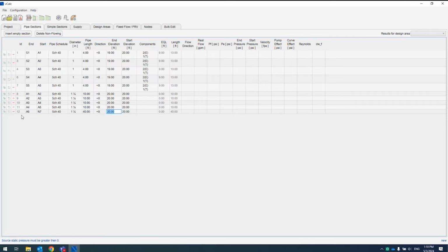So at this point, you can continue working your way back out the system. So maybe we're going to go one extra node here. We're going to go from 20 feet to 19 feet. We'll say it's still a 1.5 inch riser nipple, and it's 1 foot long. And then we can go from there, work our way back the mains. So maybe it's a 3-inch main. We'll just say it's 80 feet long. We're going to ignore inputting the other branch lines here just for brevity.